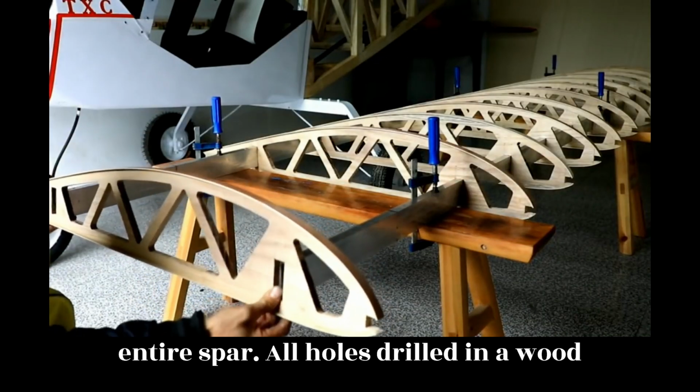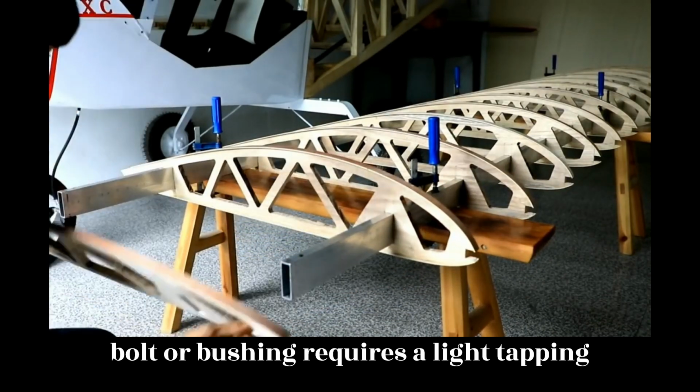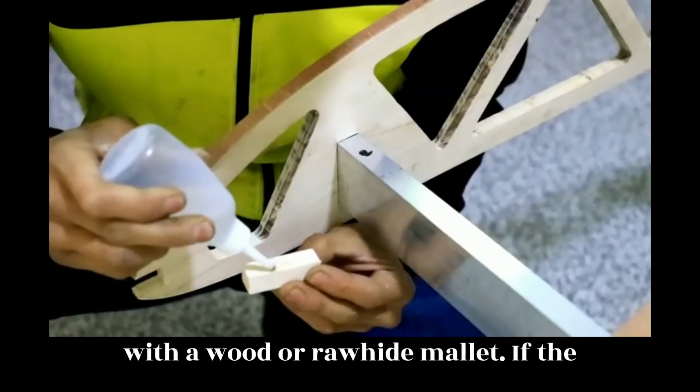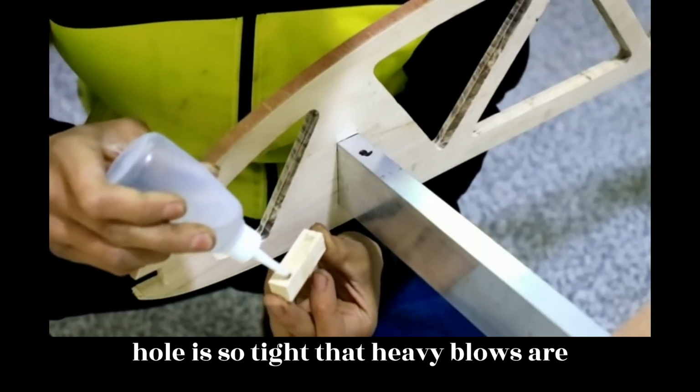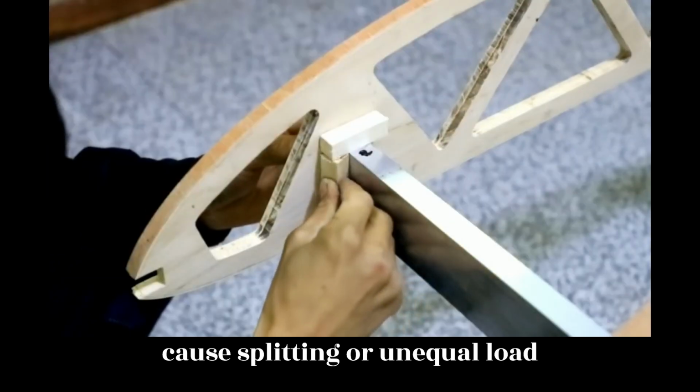All holes drilled in a wood structure to receive bolts or bushings should be of such size that inserting the bolt or bushing requires a light tapping with a wood or rawhide mallet. If the hole is so tight that heavy blows are necessary, deformation of the wood may cause splitting or unequal load distribution.